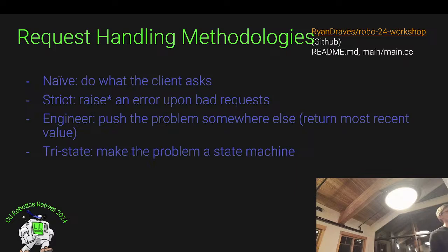Your setup changed, and so you're looking for something different. How so? Like you're measuring at a different place, a different distance. So yeah, you're returning fake data essentially, right? You know, something might have actually moved, but instead of you sending the request for the measurement, you just return the previous value. So this is maybe okay if you're running fast enough where this doesn't matter. Like your robot's moving slow, but you're pulling the measurement fast enough that it doesn't quite matter. Maybe it messes with your localization algorithm.